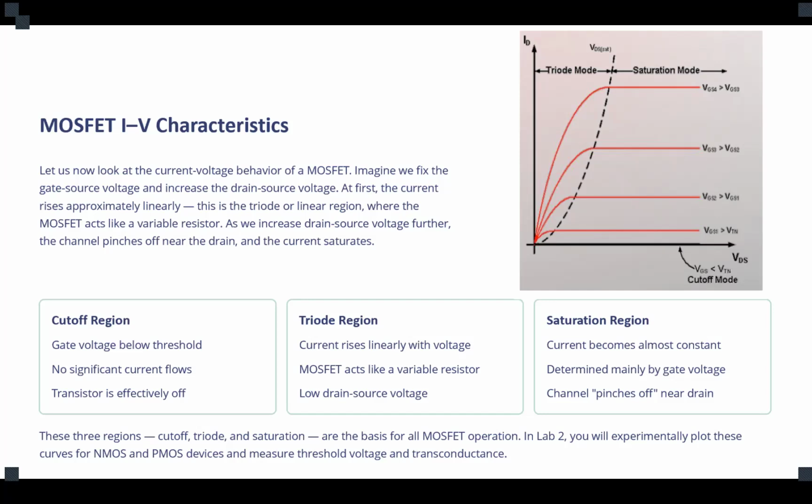Now, remember, it's not that every positive voltage would turn on the switch. There is a threshold. You have to have a certain amount of voltage between gate and source above that threshold, which is defined in the datasheet. And you can actually test that when you have the switch, to see how much voltage you have to apply between the gate and source so the switch is conducting.